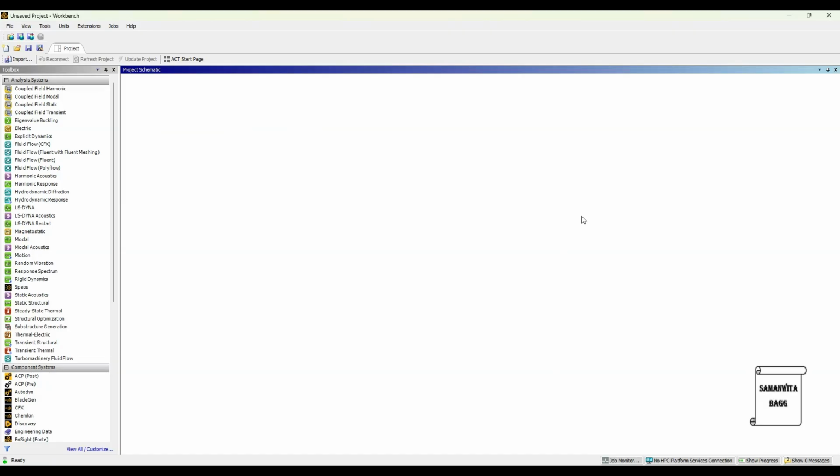Hello everyone, welcome to the next session on ANSYS CFD tutorials. In this session, we will analyze the branch pipe which we have created in the previous session. We will start by double-clicking on Fluid Flow Fluent.